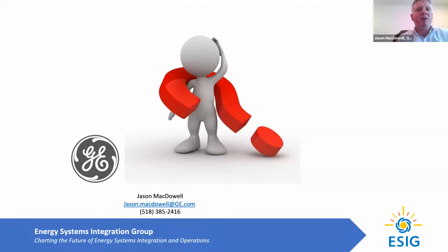There was a FERC order some years ago that requires frequency support, primary frequency response, from all resources on the grid that are bulk connected. So since that happened, the frequency support from all resources is required. And so that change really allowed all of the capability to be deployed on the grid.